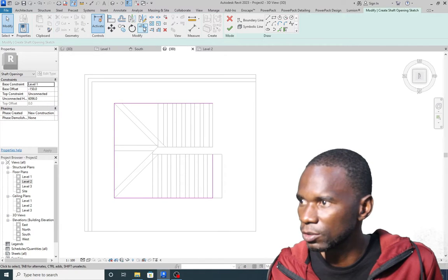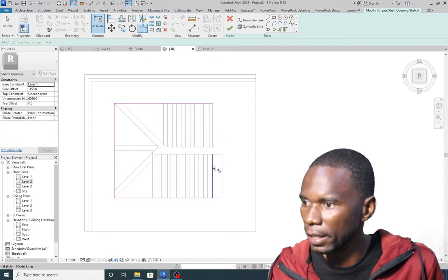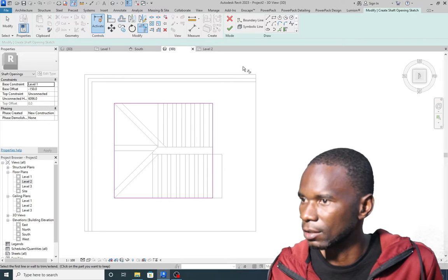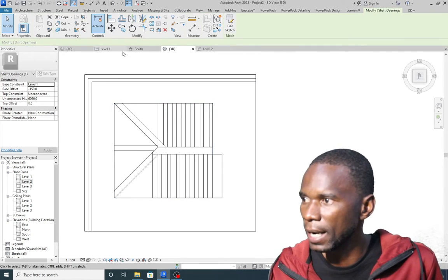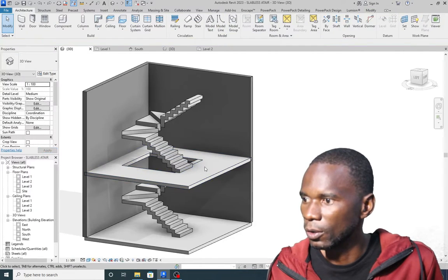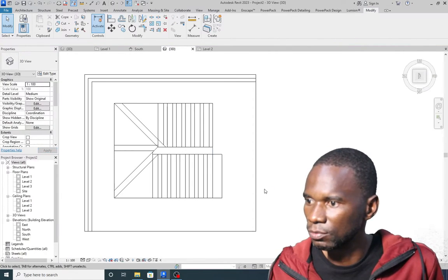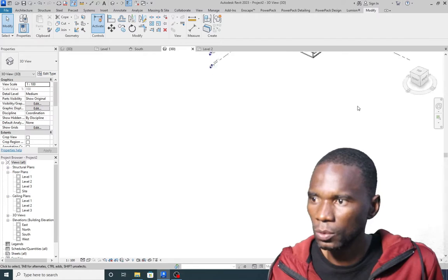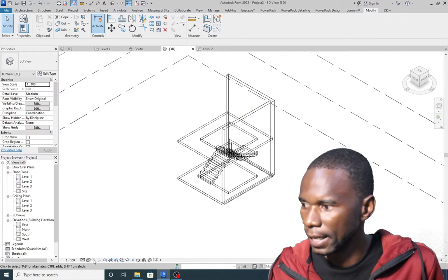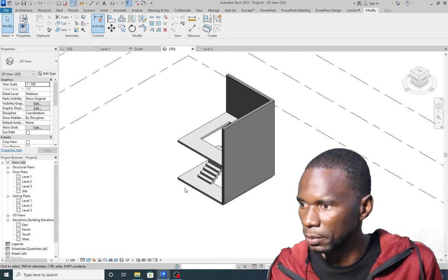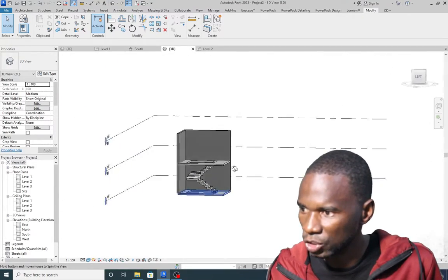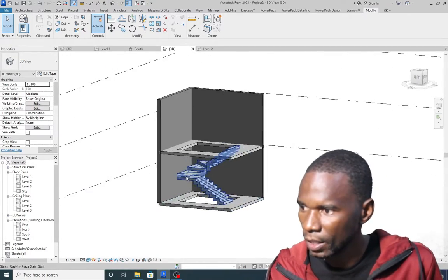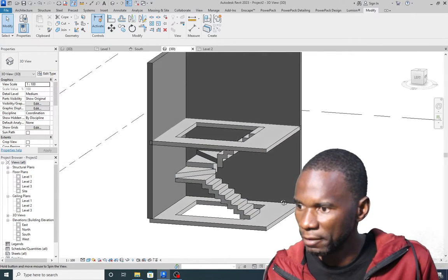If you want, instead of using TR, you can even pick it from there, click those and click on finish, that is the green check mark. Then go to the view I created, use this view, then go to that little house on top there and change to shaded, because I went to wireframe. As you can see, the opening is right there and everything looks perfect.